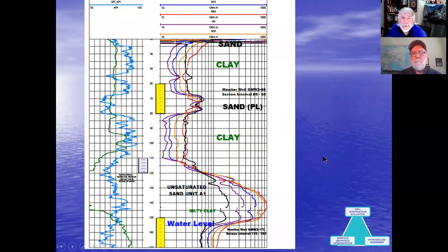So one final thought that I'd like to add, John and I mentioned earlier, the importance of running caliper and potentially directional surveys. We also highly recommend that you log your hole all the way to surface, because in this case, a lot of people will stop their logging run right here at the water table. And we can see here at the water table, which is typical, our resistivity curves, because now we're in the vadose zone of air, the curves just all break to the right, and we lose our signature of SP.